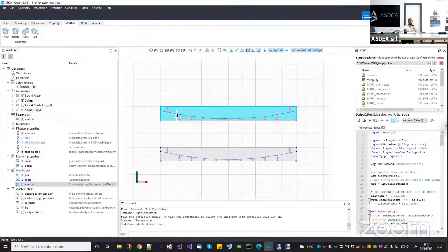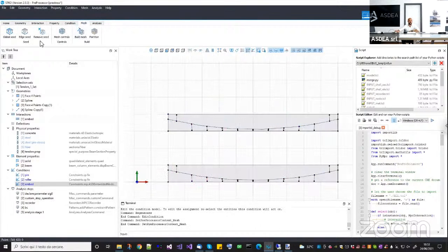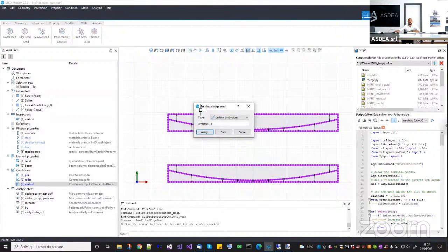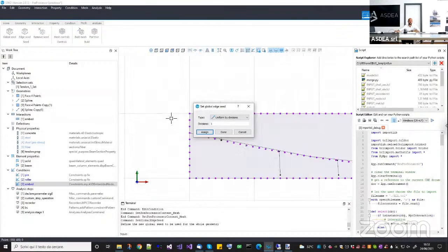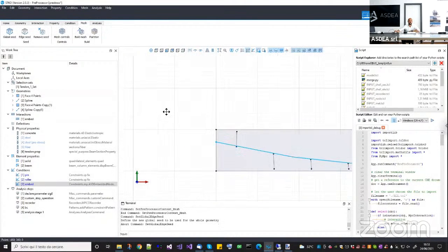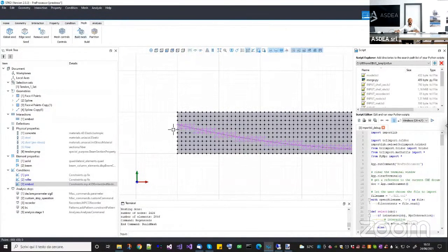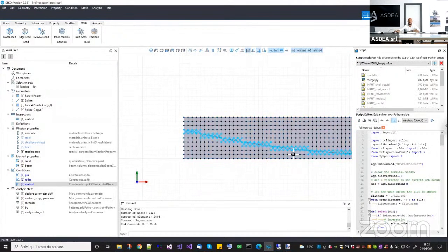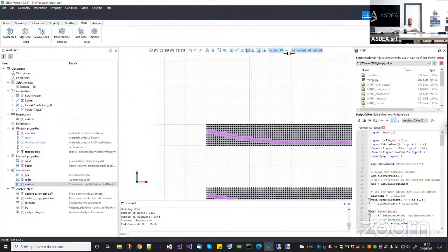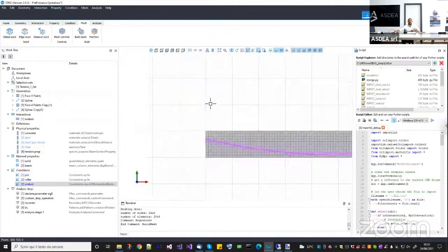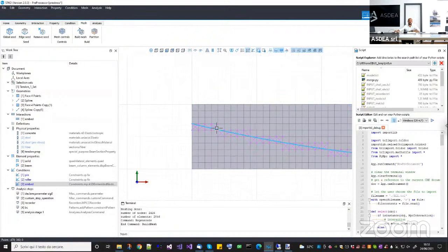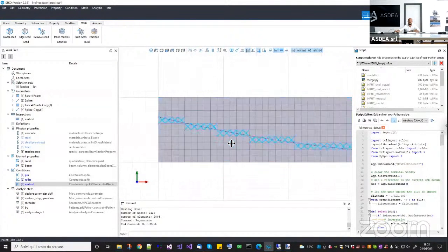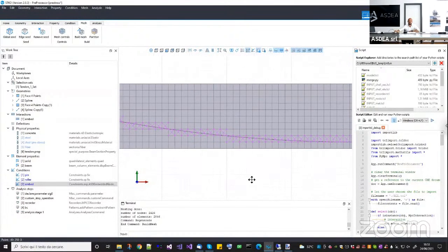I want to show you how this constraint looks when you mesh it. So you are here, you choose a global seed of whatever, I don't remember, it was 10. Then you mesh it, and now you can see that each and every node is connected to the nearest element. Here it is much more visible because the cable is curved, so you can see how each element is connected to the nearest embedding domain. Okay, this is pretty clear.